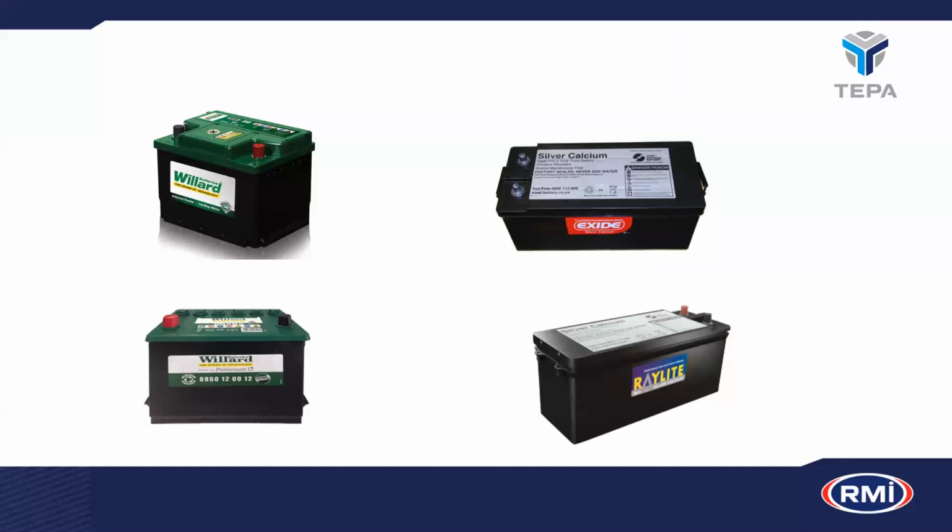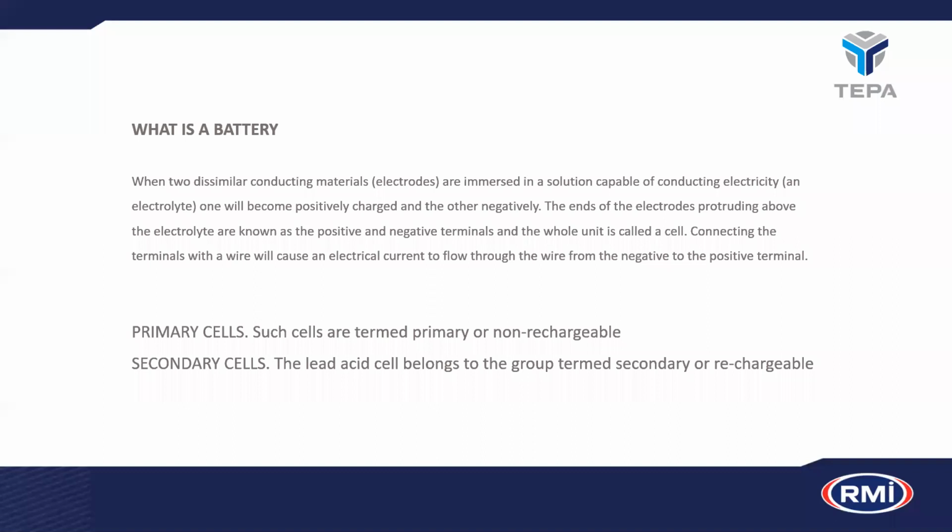And you might see in some of the bigger trucks, they might have 4 batteries together. That's not necessarily making it a 48-volt system. It's making it a 24-volt system with two pairs of batteries in parallel, giving you a much higher amperage, which is obviously valuable in cold starting conditions with a big diesel engine. So what is a battery?